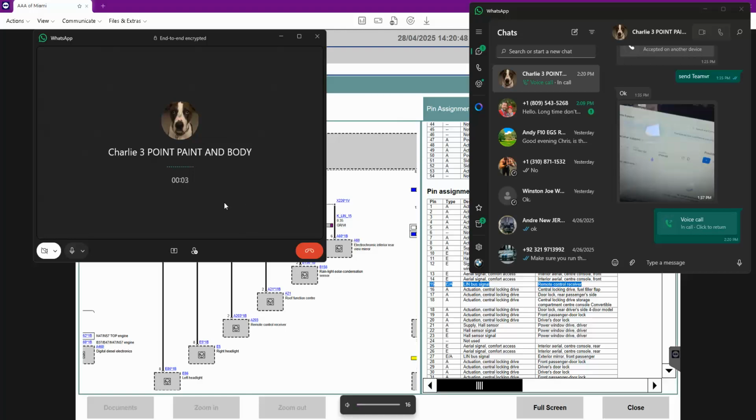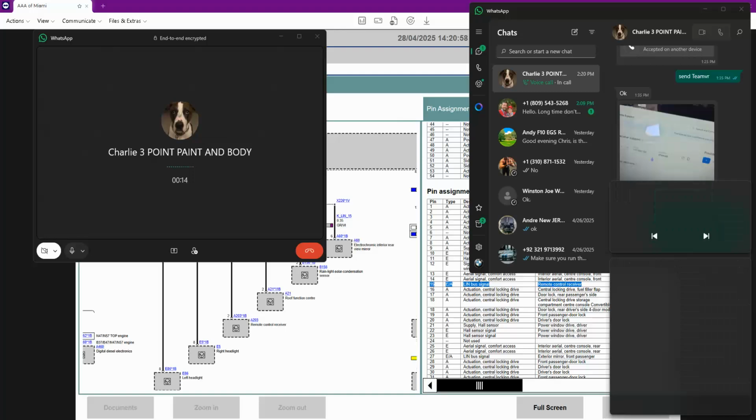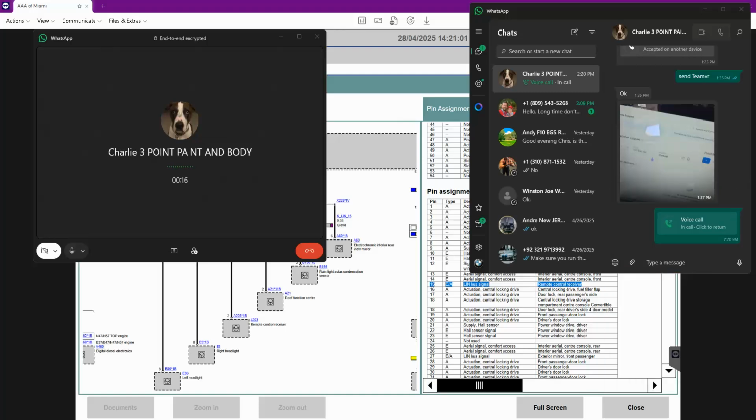Charlie. Yo, this BMW we're working on now, was the BDC programmed by me, or the FEM, or not? What happened with the FEM? Is it new on the car? Is it something I programmed, or is it an old FEM? No, it's the original FEM, it was never damaged. Yeah, but look here, I found a problem with the remote control receiver. Was there no communication with it? Yeah, no communication on the LIN bus wiring.